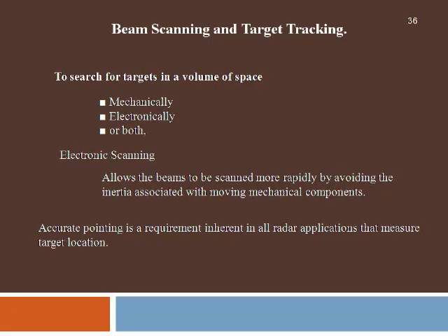In electronic scanning, the antenna should not be moved, whereas the beam must be able to move to different locations. Whereas in mechanical scanning, the antenna will be moved to different locations by using motors, and the beam will be pointed in different directions.